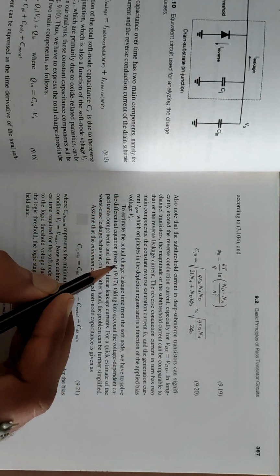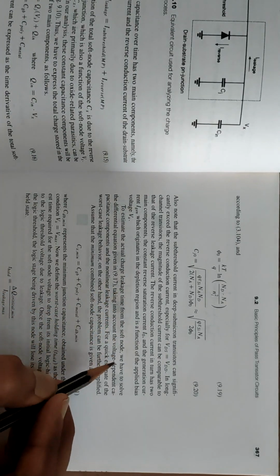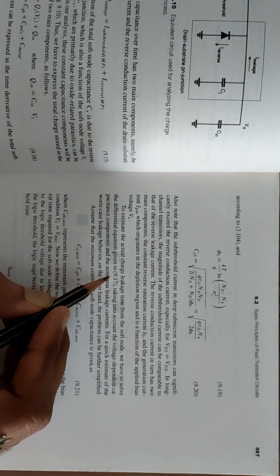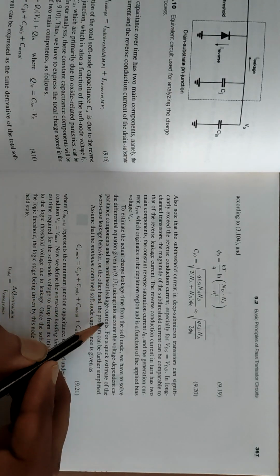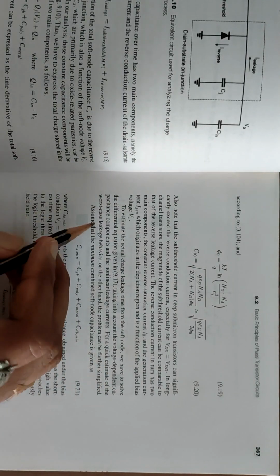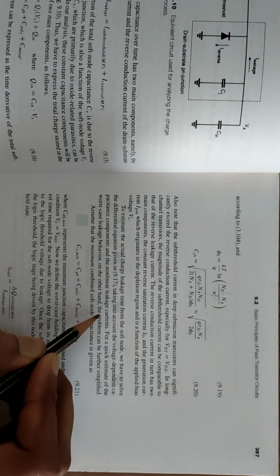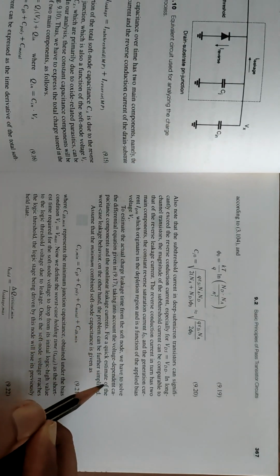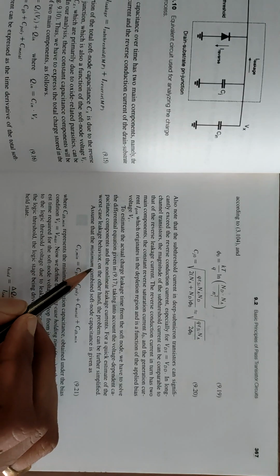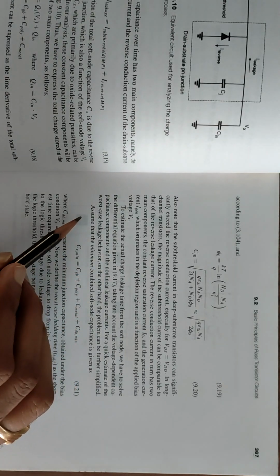To estimate the actual charge leakage time from the soft node, we have to solve the differential equation given in the equation, taking into account the voltage dependent capacitance components and the non-linear leakage currents. For a quick estimate of the worst case leakage behavior, the problem can be further simplified.